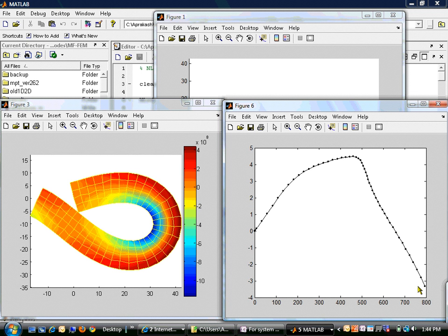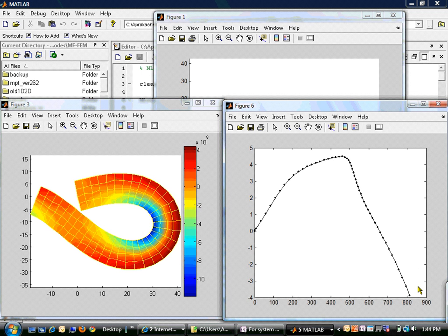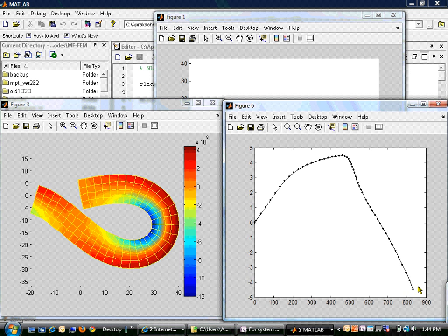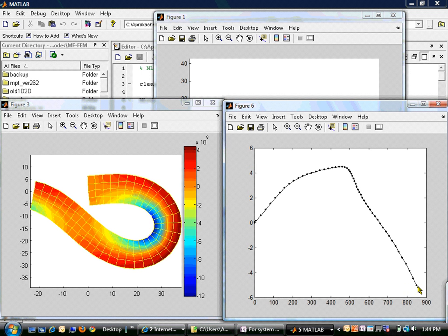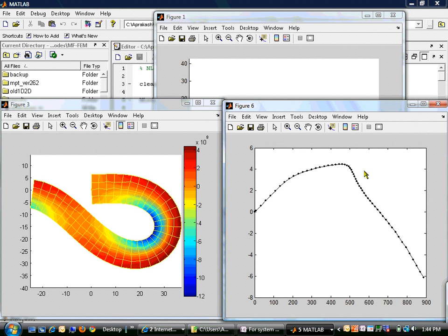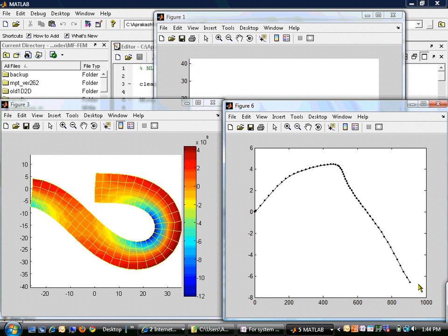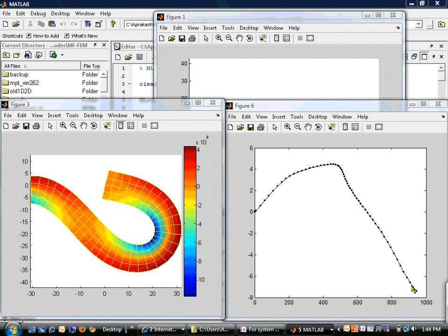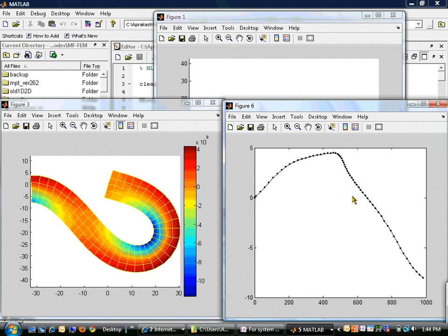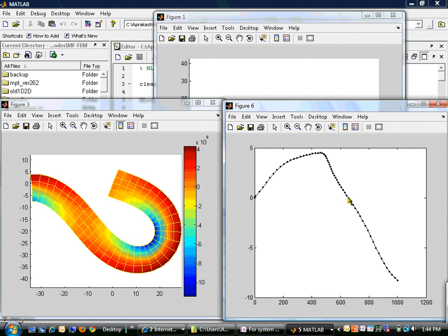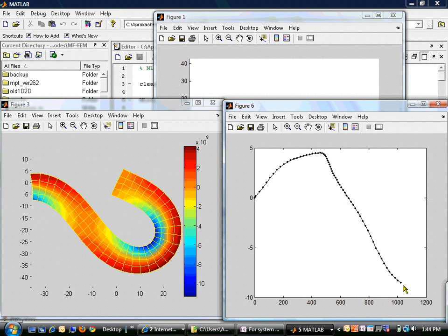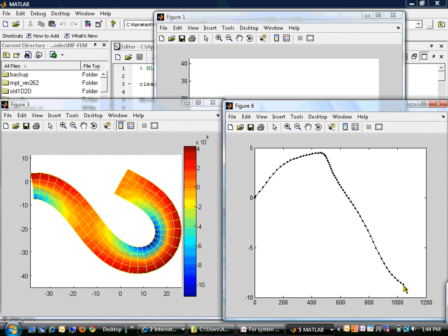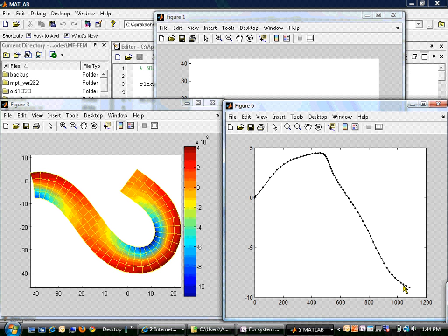And then if you finally get that Abaqus failed to converge or something, that doesn't mean that the entire analysis is a waste. It just means that Abaqus computed to some point, but then at the final point it was not able to recover or not able to converge. So you would still have the results from all those points, even at the final point if Abaqus is not able to converge.